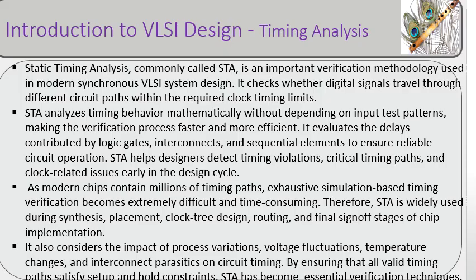It also considers the impact of process variations, voltage fluctuations, temperature changes, and interconnect parasitics on circuit timing. By ensuring that all valid timing paths satisfy setup and hold constraints, STA improves chip reliability and performance. Thus, static timing analysis has become one of the most essential verification techniques in high-speed digital VLSI design.